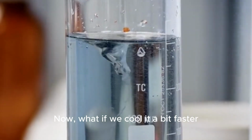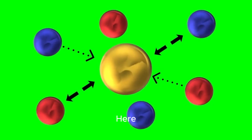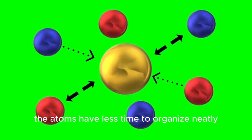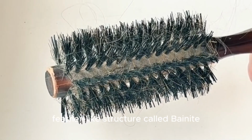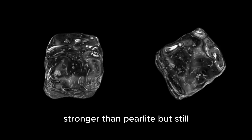Now, what if we cool it a bit faster and hold it at a temperature just below the nose of the curve? Here, the atoms have less time to organize neatly. This creates a much finer, feather-like structure called bainite. Bainite is harder and stronger than pearlite, but still has decent toughness.